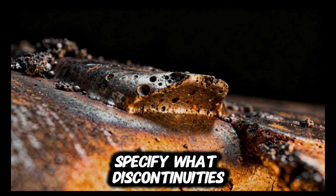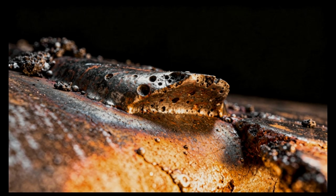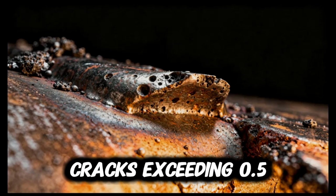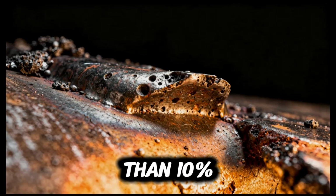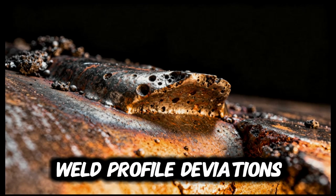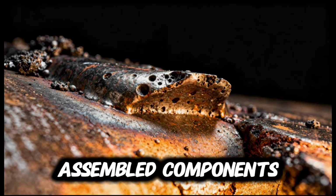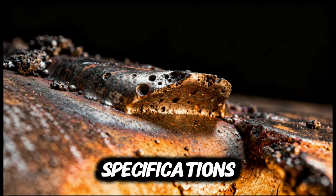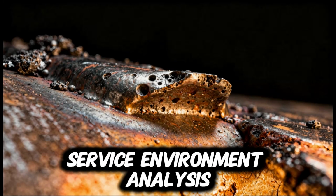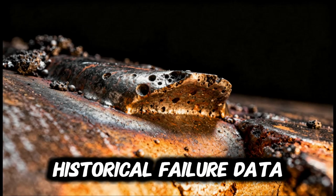Inspection objectives specify what discontinuities or conditions must be detected, such as surface cracks exceeding 0.5 millimeters, corrosion coverage greater than 10%, weld profile deviations beyond code limits, or misalignment of assembled components. These objectives are derived from design specifications, service environment analysis, regulatory requirements, and historical failure data.